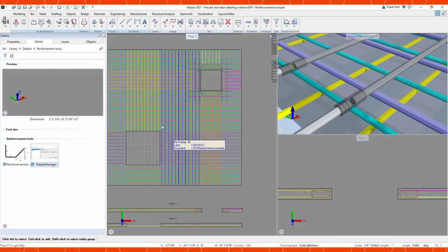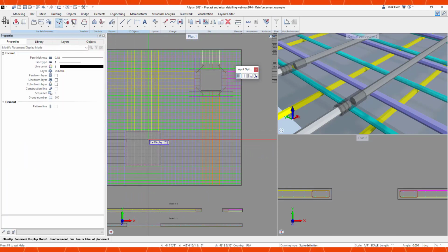A little bit of cleanup's required. So for my rebar detailers, you know that usually you only want to see the middle bars, you want to select certain bars, even sometimes you want to fold the bars. So this is great. I can just go through and select which bars I want to see for which placements, or in this case I'm just selecting the placements and telling them that I want to see just the middle bar for each of these placements here.